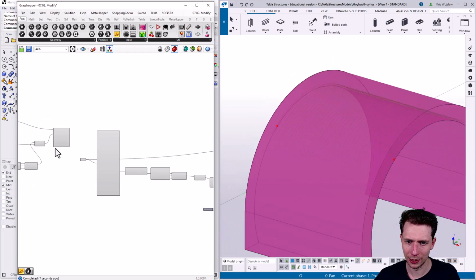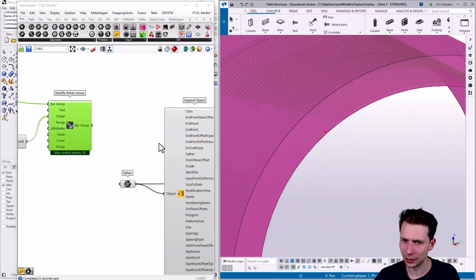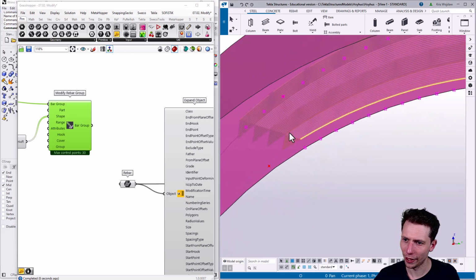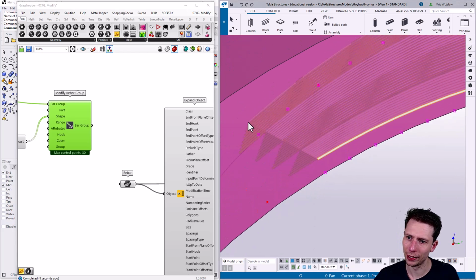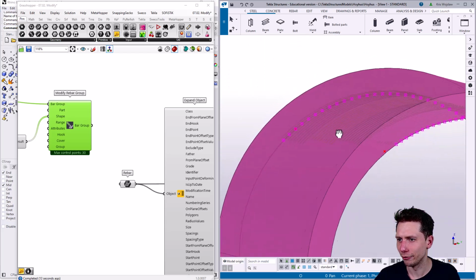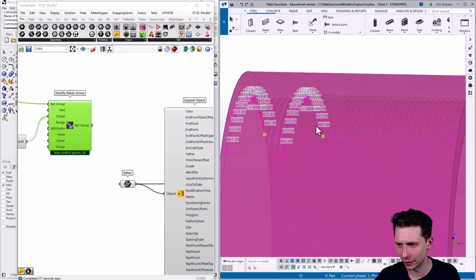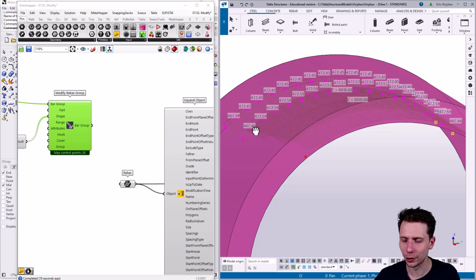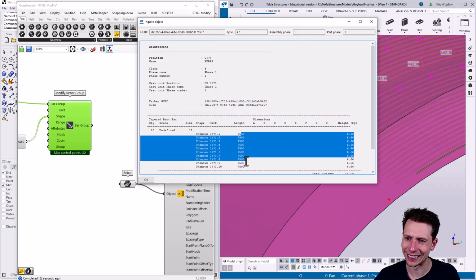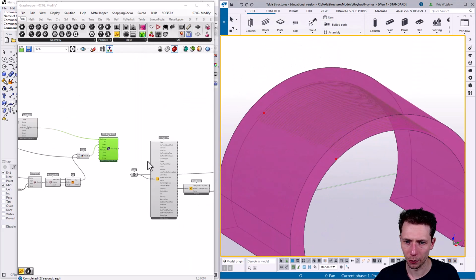So let's make again the reinforcement from before. Let me see, I will just point it out. So now, instead of having this reinforcement that is a tapered form, we have changed it into different heights, different lengths, sorry. So this is a really cool way to simplify your reinforcement. And if we go to inquire, we have the same length. And of course, we can play a little bit, we can get even more.